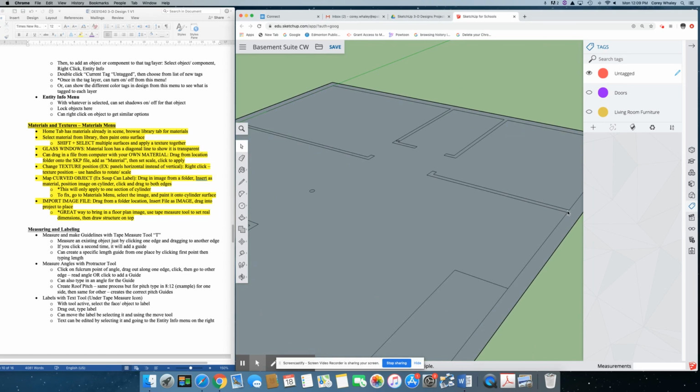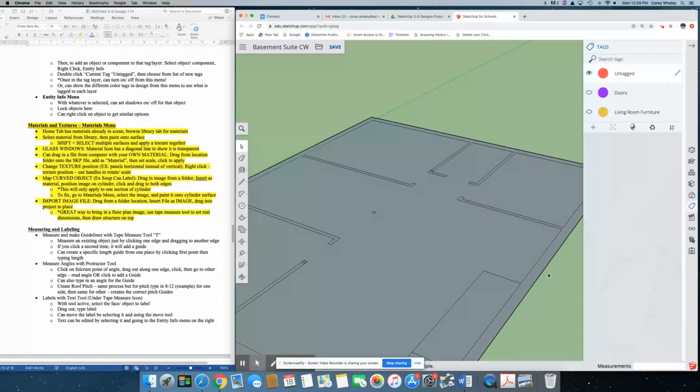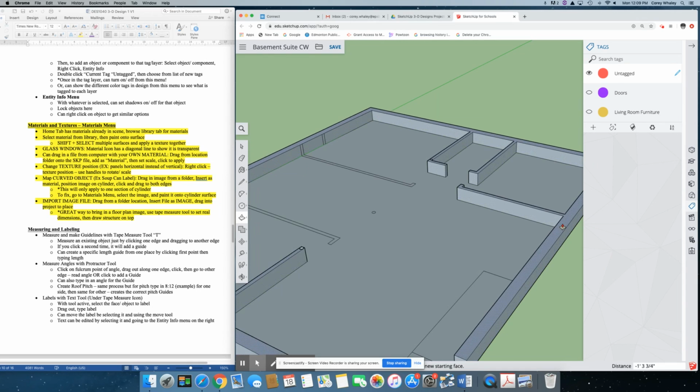So I took the eraser tool and erased just so that all of these walls were connected. That telepost circle may be in the way. But what I'm getting at is you should be able to use your push-pull tool and go over this surface, and you can see there's a bunch of things that are connected. I can see right now that those walls aren't though. So if I select this area right here and pull it all up, look at that, it's magic.